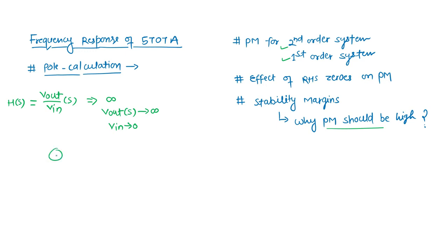What is my GM cell? My GM cell is nothing but a current source. And this current is fed into some capacitor CL, and what I want here is V out. And what is this current? Current is nothing but GM V, and this is my GM cell. So what can we write? Can we write directly V out is nothing but when this current is charging my capacitor, so CLS.